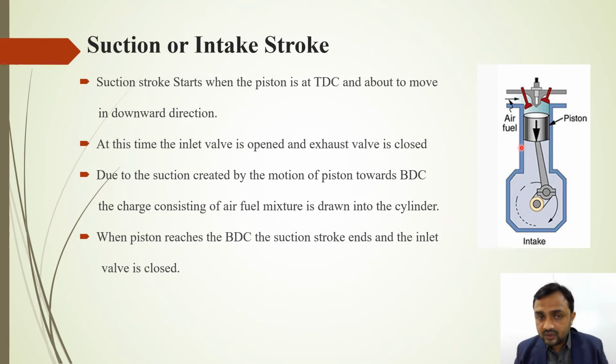Okay, what happened in your suction stroke? Now when the piston starts to move toward BDC, the air fuel mixture is drawn inside the cylinder with the help of your inlet valve. Next point is when the piston reaches the bottom dead center or BDC, the suction stroke ends and the inlet valve is closed.